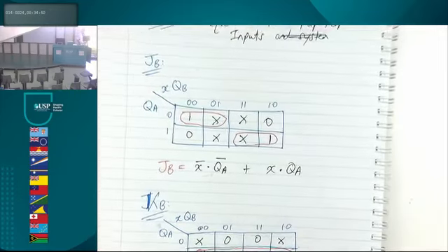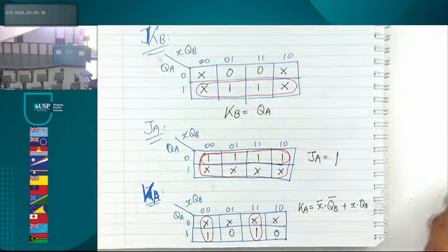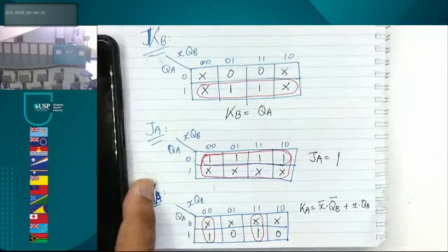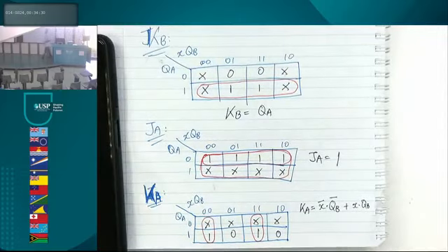So is everyone okay with how I got to this stage? How I got the 4 formulas? You see, when we do analysis, you start off with a circuit. Somebody will give you a circuit. From the circuit, what did we do? Like in the quiz, we found the equations. From those equations, we plug it into the state table. Of course, some parts of the state table are done automatically, like the input, output, depending on what the circuit diagram looks like. Then from the state table, we go to the state diagram, right?